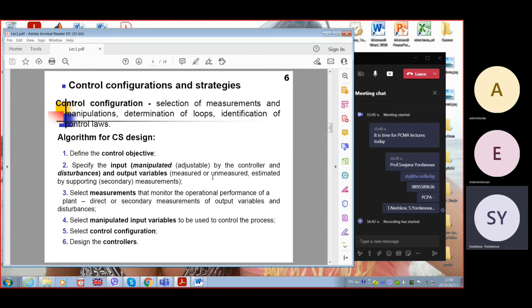It has a sensing element, some physical properties used to measure temperature. For instance, we use thermocouples, two metals. They have a hot joint between them, and the cold ends result in voltage.